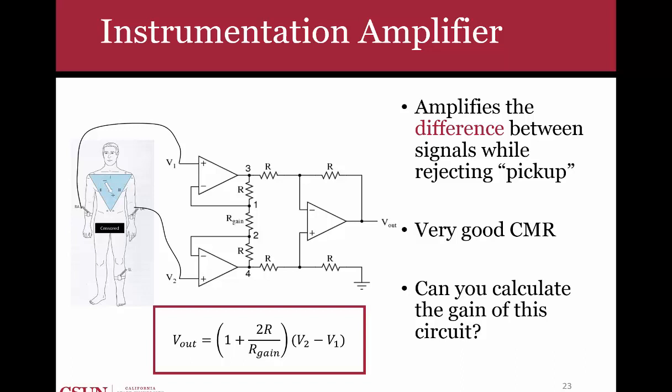Okay, so now let's go back to the actual ECG scenario we had. Let's say you're given the right arm and the left arm electrodes, and you're asked to make an instrument that, once you apply the electrodes to the body, will allow you to measure the voltage difference between those electrodes, right? Remember that the voltage difference is proportional to how parallel my cardiac dipole vector is to that lead connecting those 2 electrodes.